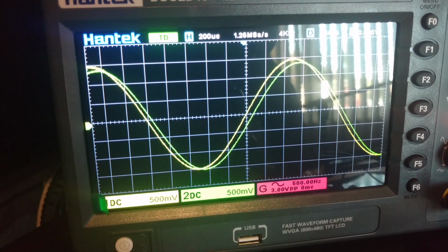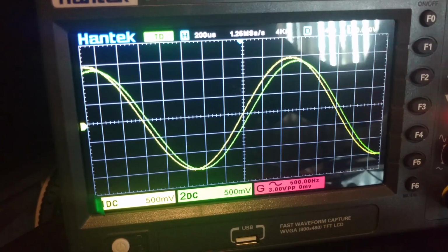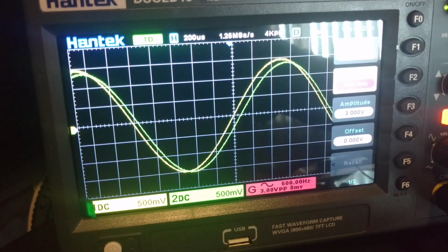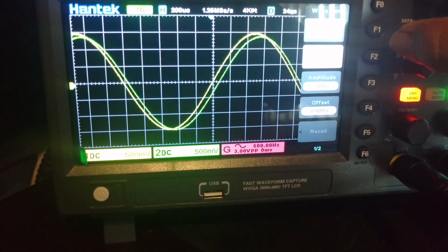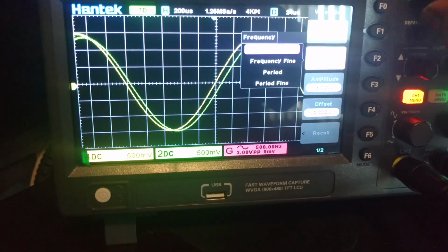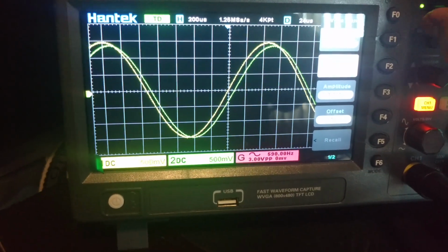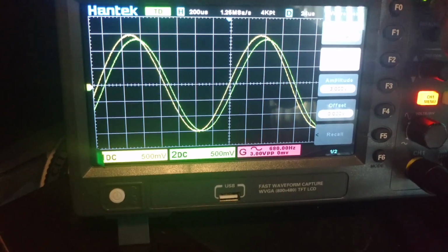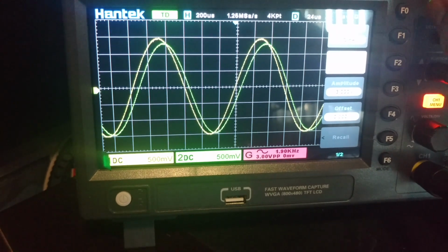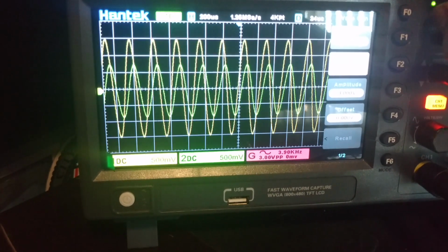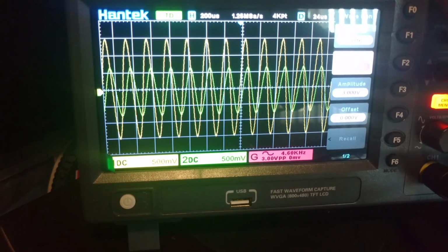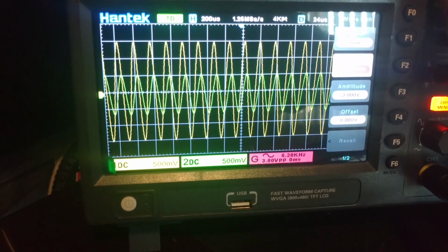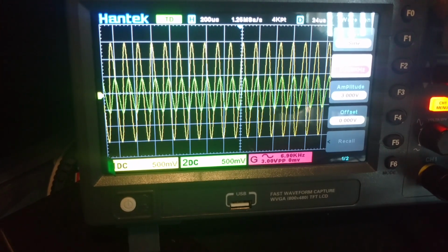which is what we calculated. Now I have integrated into my oscilloscope the actual function generator, so I'm going to go in here into the frequency and vary it. As I increase the frequency, you can see that the green curve, which represents the output of the capacitor, gets smaller. The higher I make the frequency, the smaller it gets.